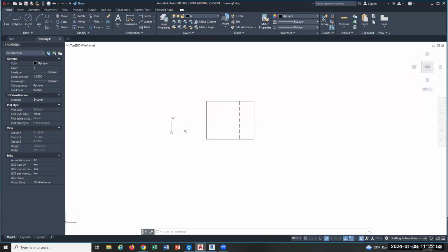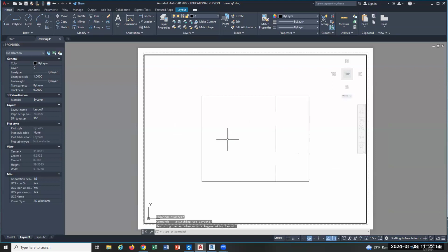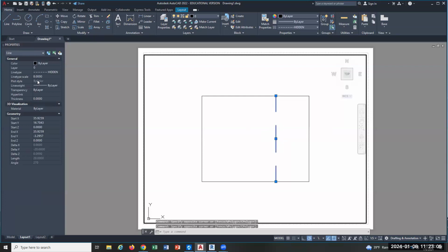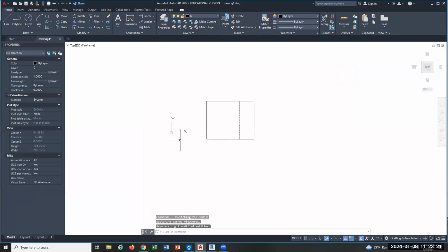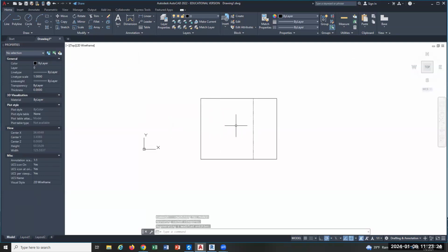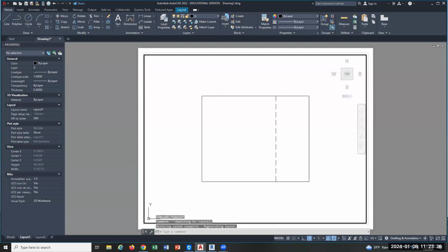You want to size your line type scale here because this is what you're going to print, right? This will be the view that you get. So I'm going to switch it back. I'm pretty sure it's going to want to go back to 1. So I'll try that. Yeah. So adjust it here because what you print here is what the customer is going to get. I'm your customer. I don't want what I had before. That means it could look pretty crappy here, but I don't care what it looks like here. We're not printing this. We're going to print from layout.